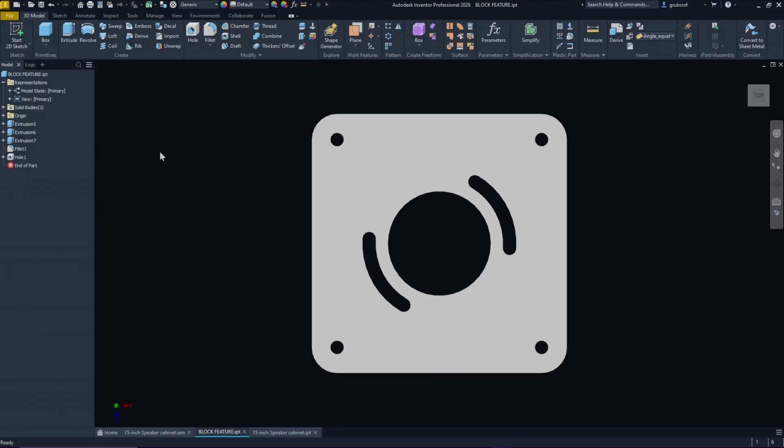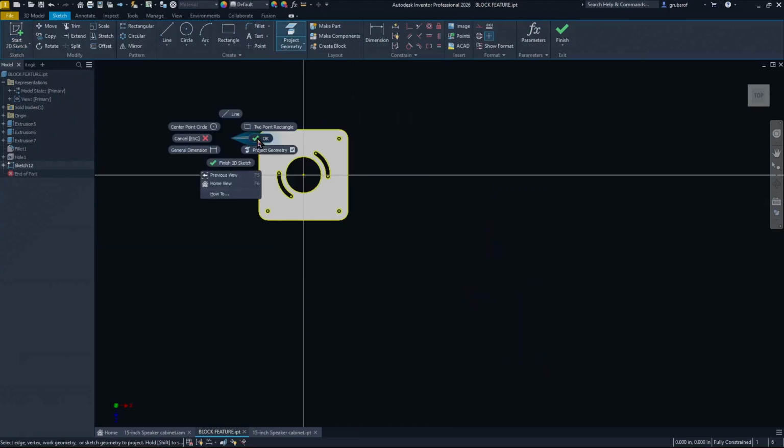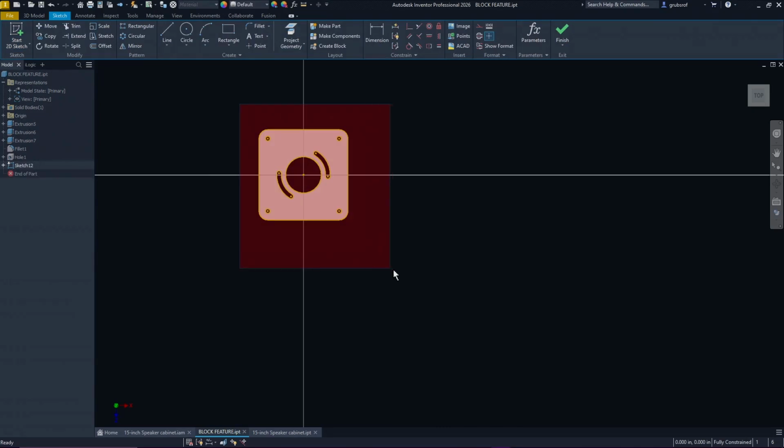So an easy trick for this is, you're in your 3D model, go to Sketch, pick the face like we're going to draw on it. Do project. Let's grab the entire piece. Say OK to that. Select it. Copy and paste. And then you have that. The exact same profile. I don't have to repeat that because this is something I'm going to use constantly, but it was developed outside of the other box.